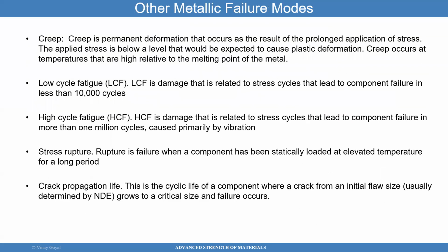I covered some of that. Fatigue failure, we're going to cover that later. Low cycle fatigue, typically low cycles to failure, 10,000 or less. High cycle fatigue, you're looking at millions of cycles.